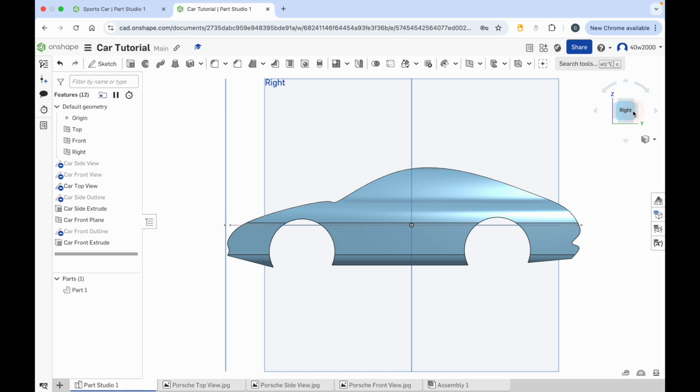So now we've done that, all you need to remember is that we can use the extrude remove tool to basically carve away at a 3D object. Whereas you might watch some tutorials that have you making complex wireframe models and then using tools like the fill tool to create new surfaces and engage in complex surface modeling, we can create simple curved shapes by simply creating a 3D model and carving away at it, very much like that 3D model was a lump of clay. And when we use the extrude remove, we can create these complex curved surfaces and just use the extrude tool to cut away material from the 3D model.